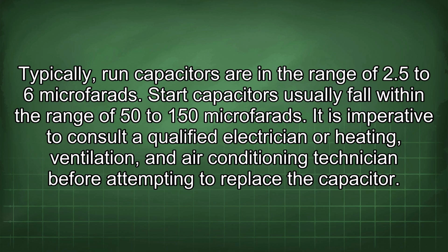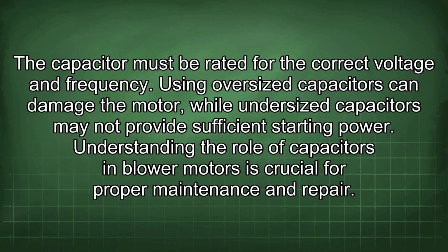It is imperative to consult a qualified electrician or HVAC technician before attempting to replace the capacitor. The capacitor must be rated for the correct voltage and frequency. Using oversized capacitors can damage the motor, while undersized capacitors may not provide sufficient starting power.